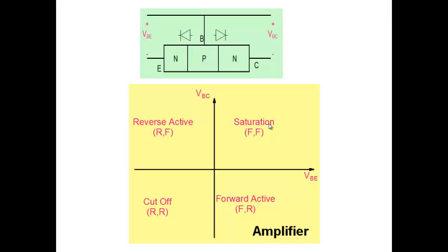Okay. Now, having said that, all our discussion will basically revolve around a transistor that most of the time will be in forward active mode. Very seldom will we find that the transistor is in the saturation region. This course is about analog circuits, and in these analog circuits we'll be discussing amplifiers only, and we'll see that to make an amplifier you want to bias it in the forward active mode. Okay, so this is the most important mode for us.